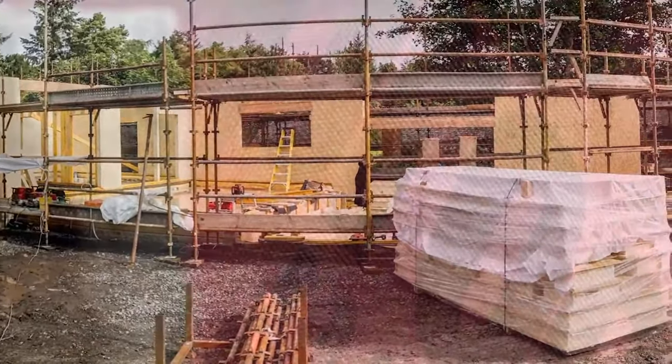Timber frame and SIP constructions typically use a range of different membranes to protect and enhance the performance of the base constructions. Usually there is a membrane fitted either side of the wall, a vapour permeable or breather membrane on the cold side of the wall, and a vapour control layer on the warm internal side.